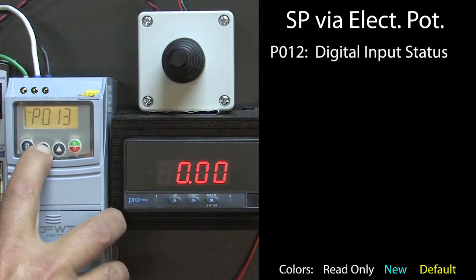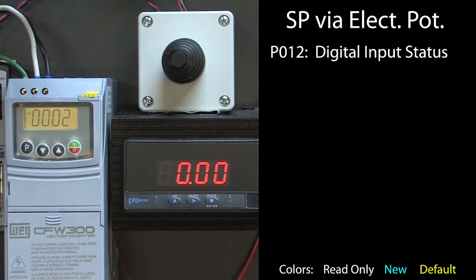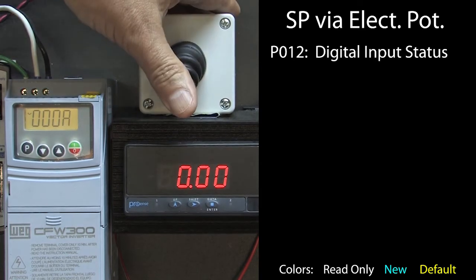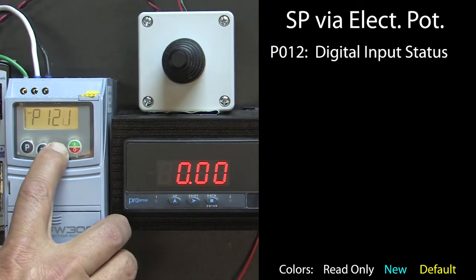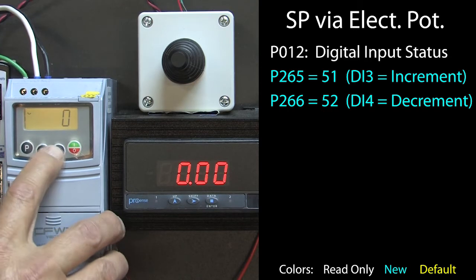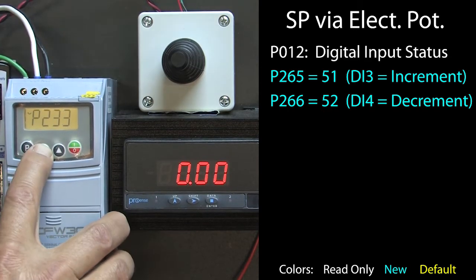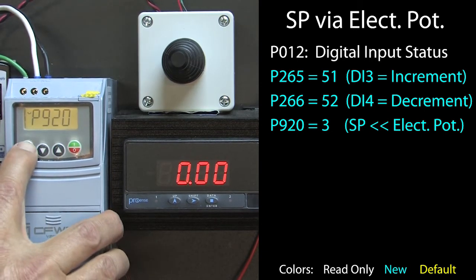Let's go to parameter 12, which tells us the status of the digital inputs. Push the joystick up, and yep, the 3rd bit lights up, giving us a 6. And if I push the stick down, the 4th bit goes active, which gives us a hexadecimal A. Perfect. We now know we wired it correctly. Parameter 265 is where we tell the digital input 3 it'll increment the potentiometer, and parameter 266 is where we tell the digital input 4 it'll decrement the electronic potentiometer. Of course, we need to go to parameter 920 and tell the PID application to use the electronic potentiometer for the set point.